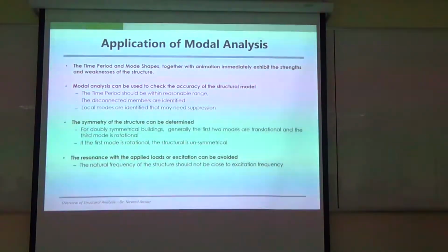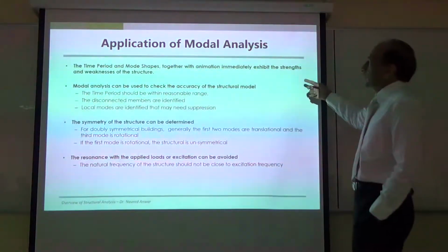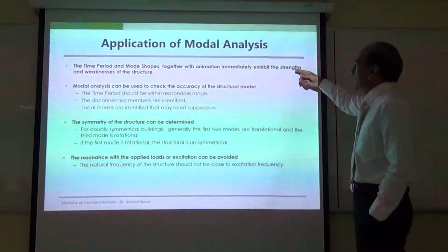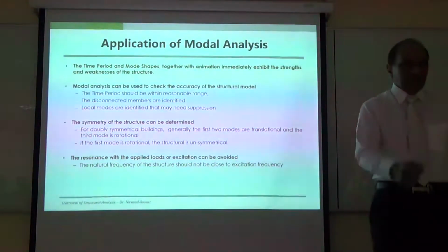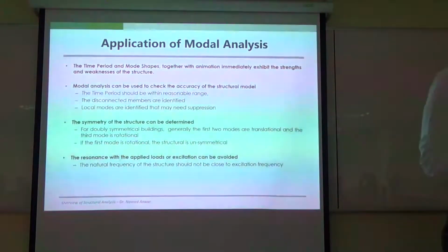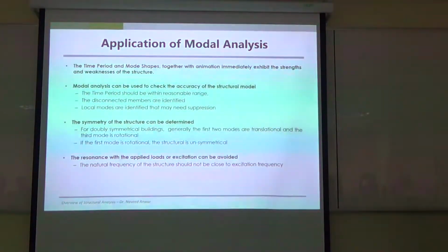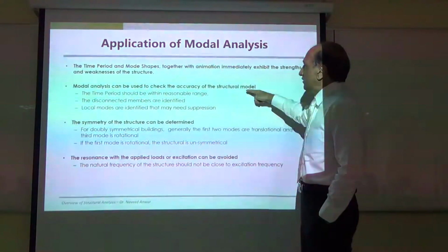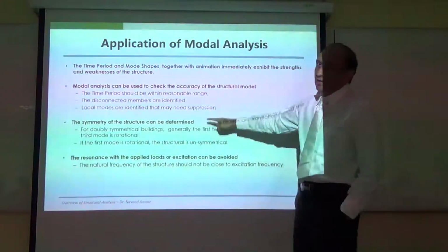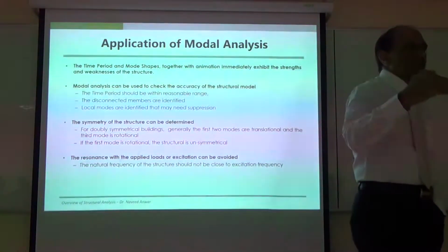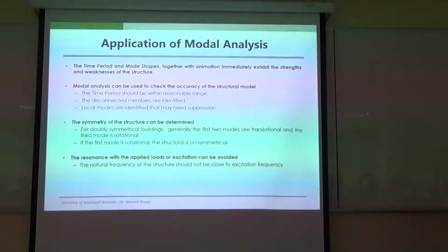Application of modal analysis. The time period and mode shapes together with animation immediately exhibit the strength and weakness of the structure. So by looking at that, you can see where the structure is strong, where it is weak, what is the weakness, what is the strength, right? It's a matter of understanding. Modal analysis can be used to check the accuracy of the model. So if the natural periods are within a range, that means your building and model are okay.